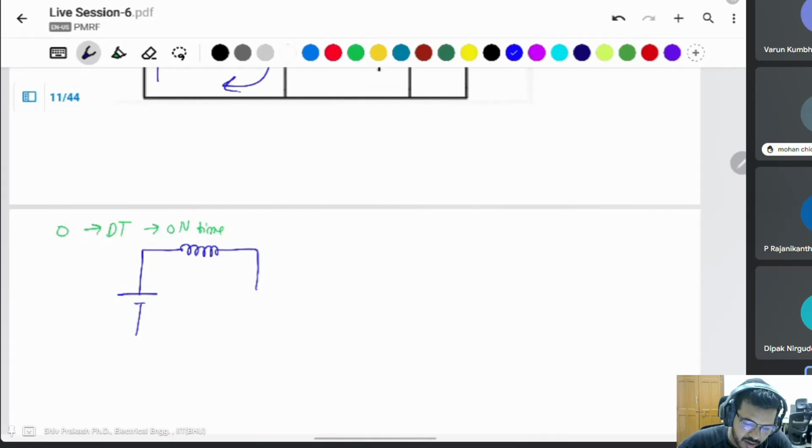Switch is on, then the saturation voltage is 0.2 volt, so this voltage will also be included here. This is 0.2 volt. I retain a voltage drop VQ for this. So voltage Vs, and calculate the VL: Vs minus VQ.